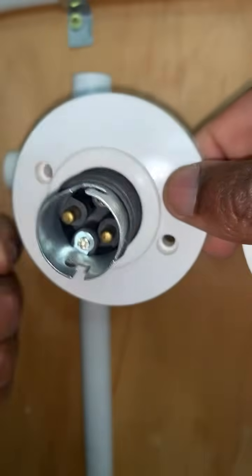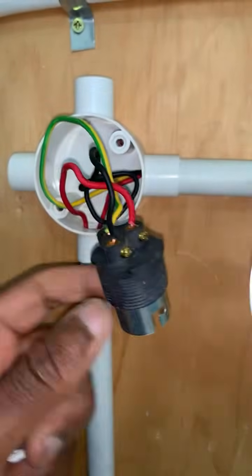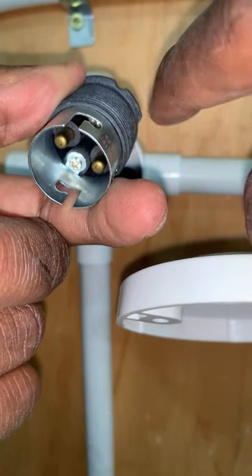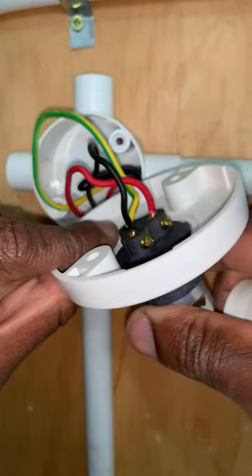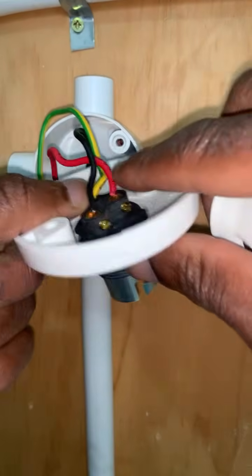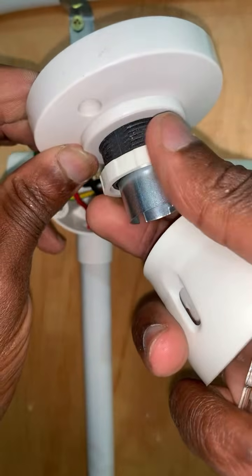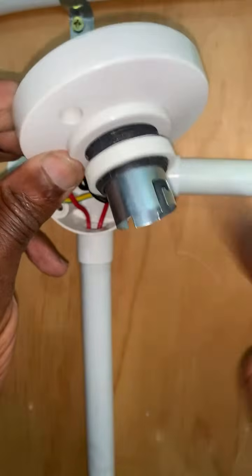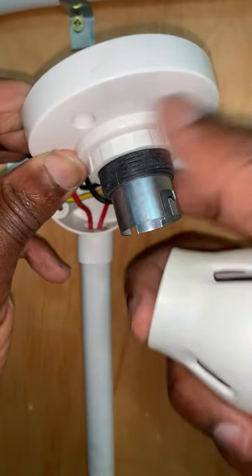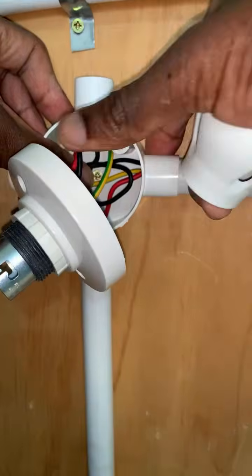our bulb holder. Another thing to do is to ensure that you understand the bulb holder correctly. You see these notches here have to pass through this notch here. See that, so that it will become easier for you to connect. You see that one there. And so you take this, then you simply screw, like that. Make sure that you reorganize the cables inside.